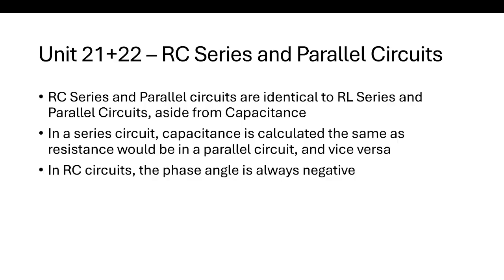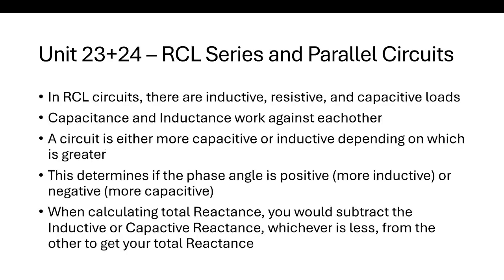So RC series and parallel are identical to RL series and parallel, aside from your capacitance. Again, in series, your capacitance is counted as a parallel would be, and in a parallel, it's counted as a series would be for other resistors. You should get it by now. The big difference is that in RC circuits, the phase angle is always negative.